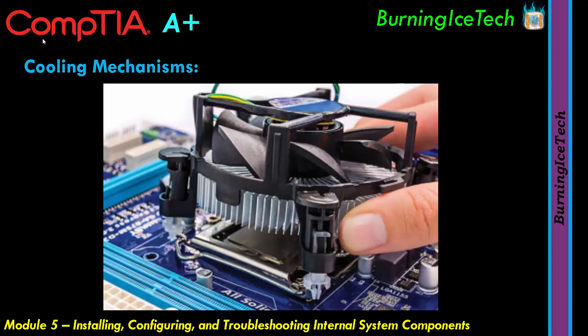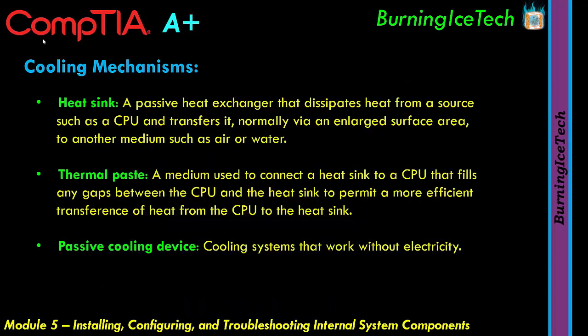So what this is going to do is it's going to allow the heat to transfer just so much better to that heatsink. It's not that it's not going to transfer at all. It probably would have transferred a little bit to the heatsink, but not as much as you would like. So the thermal compound is just going to transfer the heat a lot better. It's a very good heat conductor. It allows it to transfer the heat.